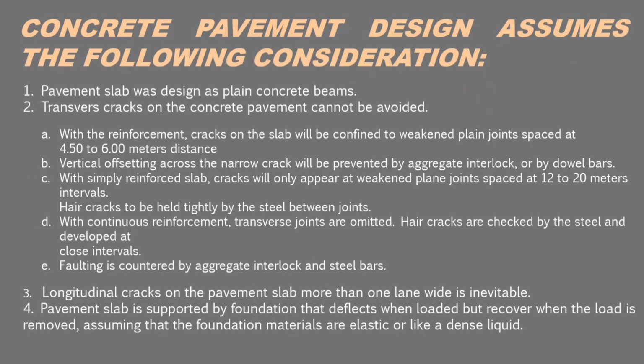There are also considerations in concrete pavement design. 1. Pavement slab is designed as plain concrete beams. 2. Transverse cracks on the concrete pavement cannot be avoided. A. With reinforcement, cracks on the slab will be confined to weakened plane joints spaced at 4.50 to 6 meters